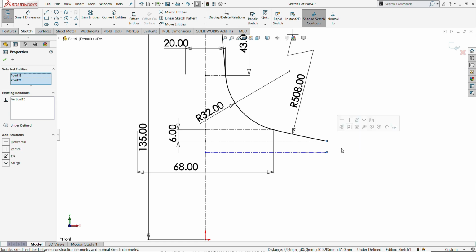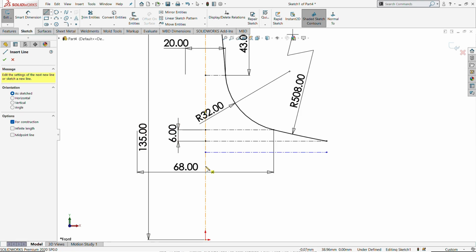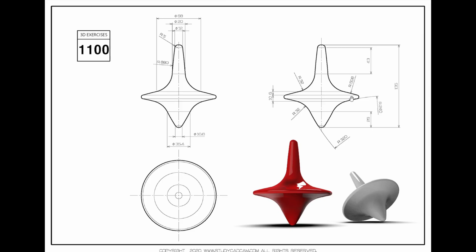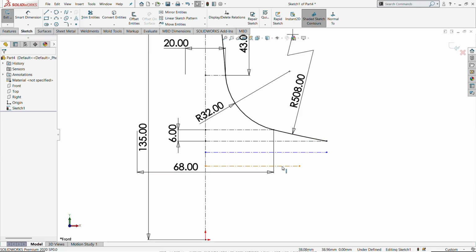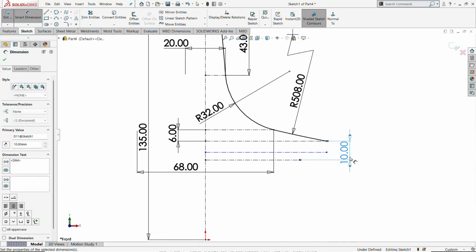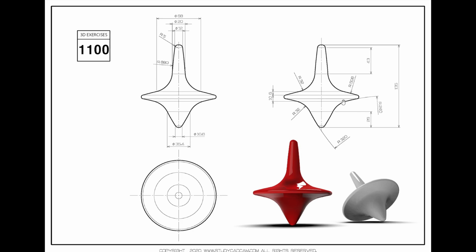Once we draw a horizontal center line, now fix it using a vertical constraint up to its endpoint. Then draw another horizontal center line profile. Okay, what are the dimensions of it? It doesn't have enough horizontal dimensions, but the vertical dimension is positioned from the end of its 6 mm; assign the vertical dimension 10 mm. We don't have enough dimensions to fix this horizontal value.